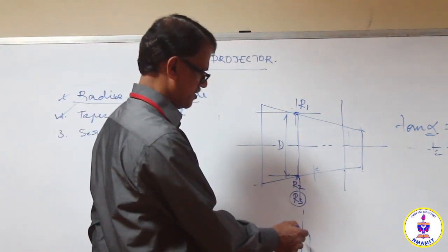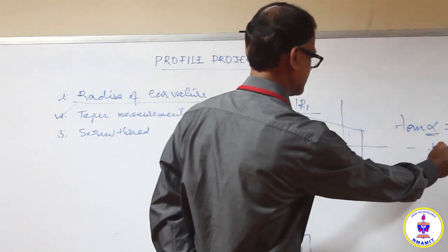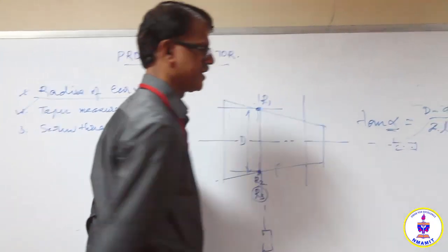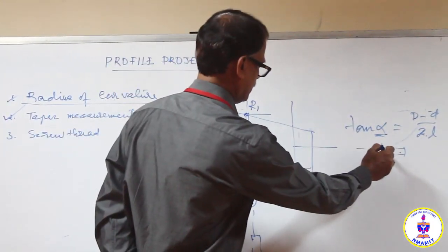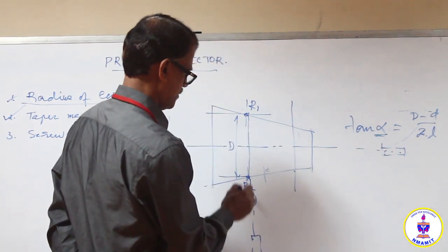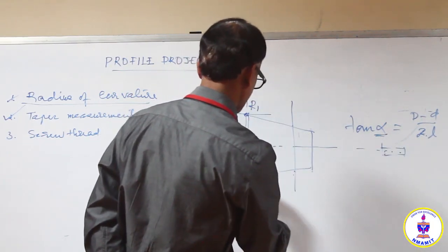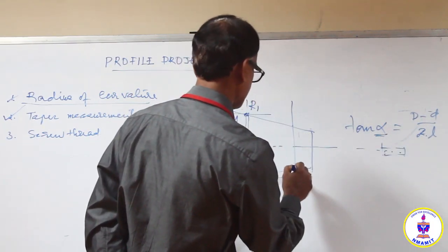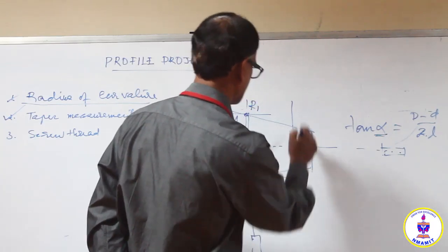So this micrometer is not disturbed now. Crosswire is here, and here itself on this micrometer, second micrometer on the longitudinal axis, record the third reading, that is the initial reading for the length. Now move this micrometer to the new position here. Say camera to the next section.